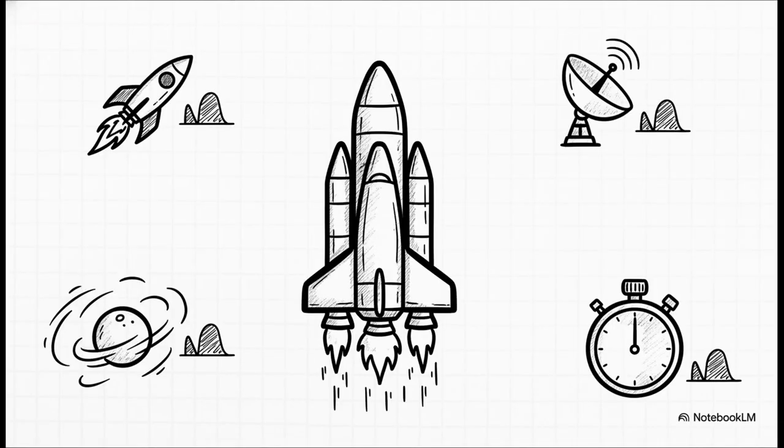Step 1 is where we literally acknowledge what we don't know. We list our uncertain inputs. In a complex machine like a spacecraft, for example, this could be thrust uncertainty, a slight bias in a navigation sensor, unpredictable atmospheric orbital drag, or tiny, microscopic clock errors. Instead of assigning a single fixed number to these factors, we assign a probability distribution to each one. Essentially, we map out the boundary of our doubt.